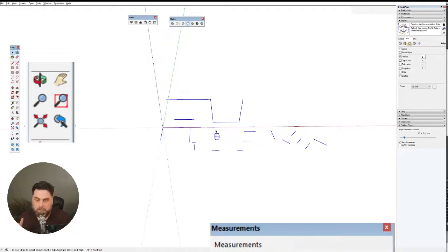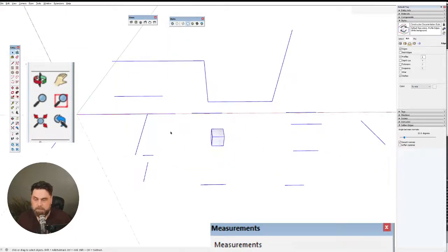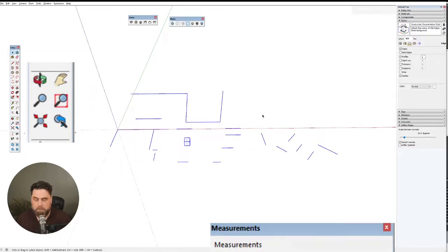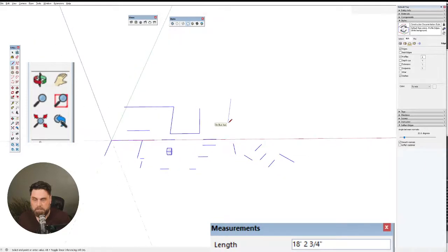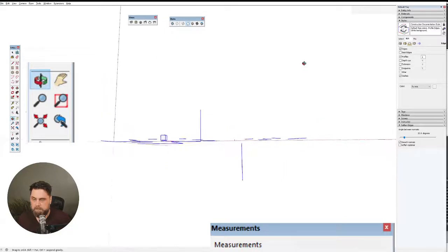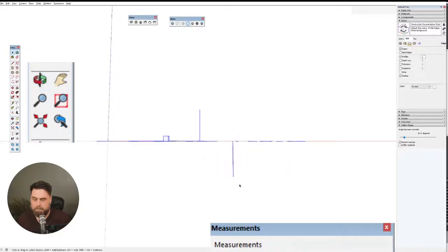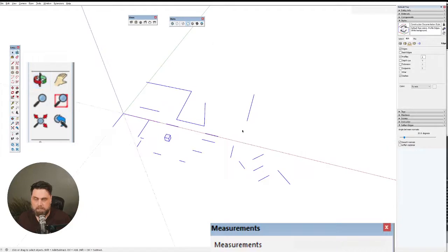And then go in and practice just drawing out some edges with your by-axis color turned on, and just get familiar with it. Look for the indicators, look for the red, look for the green, and maybe just try to practice drawing out. Because it's really tricky. I'm here in this perspective and I look like I just drew an edge and it snapped to something, but you don't realize from this viewpoint that you just made a line that was down into the ground. It doesn't look like it because it's an optical illusion.